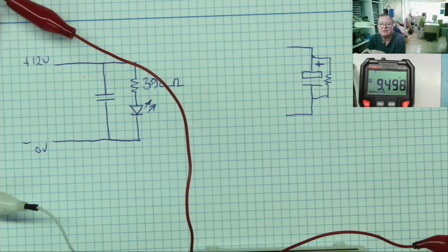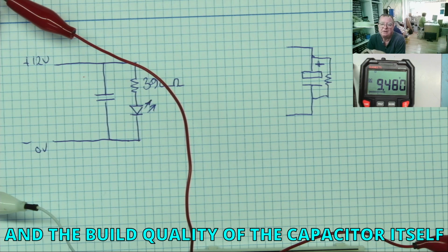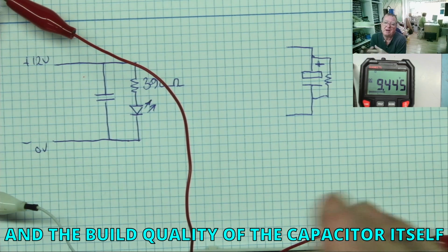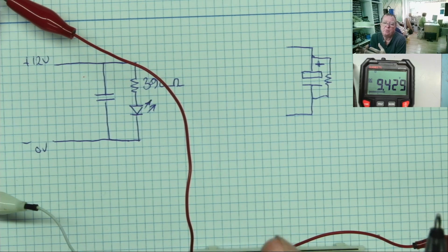And when I say a very long time, this depends on the voltage that's in the capacitor. This is why you've probably seen these warnings on high voltage mains powered electrical equipment, that if you open it, it may contain high voltages when it's not connected to the mains. And this is why, because capacitors in that sort of equipment can charge up to 300, 400 volts. Yes, I know your mains is 110 or 220, but there is often a booster circuit in there to increase the voltage. We'll talk about that much further down the line, but for now, know it's there. So it's quite possible to have 300, 400 volts stored in the capacitors in a piece of mains powered equipment for a very long time afterwards.